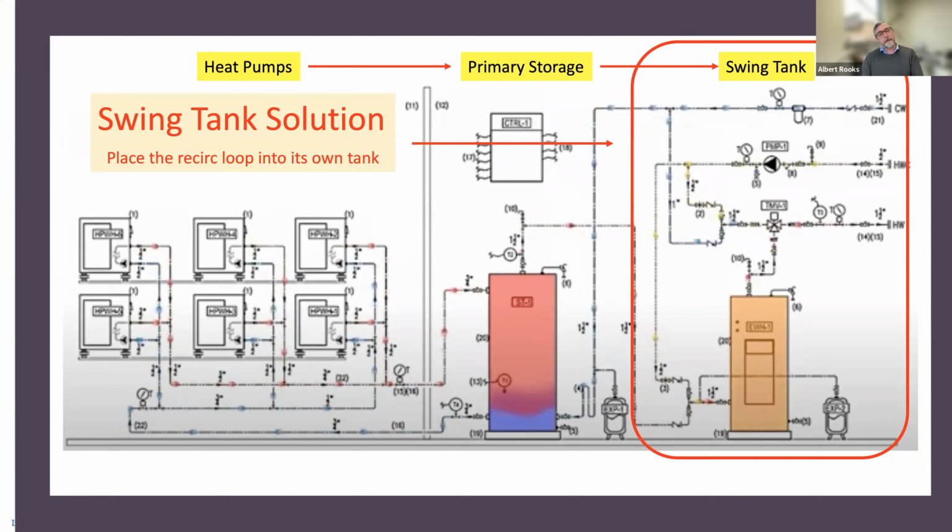And when you need the final lift is when people start waking up and making a draw on the building. Then we're starting to pull water out, and it's going to go past the mixing valve and start getting used. It might be cooler. So when that draw starts happening, or during the final stages of the recirculation draw, the electric resistance will flash on, do a final lift, get it above its mixing point.